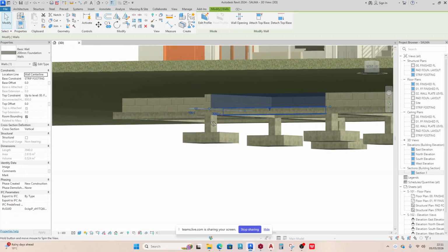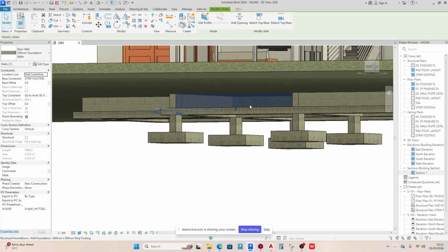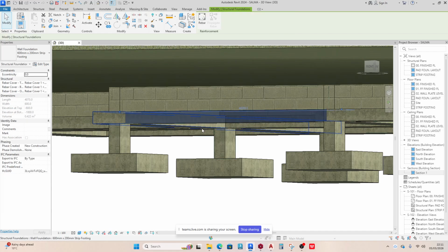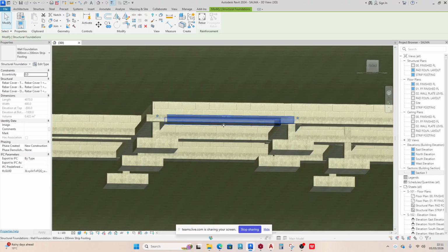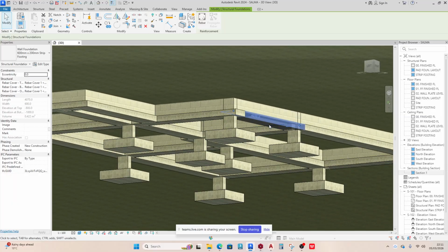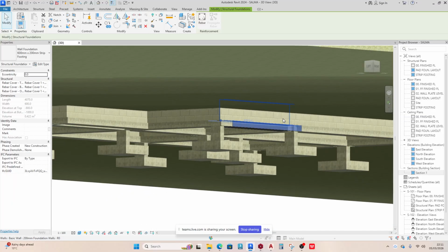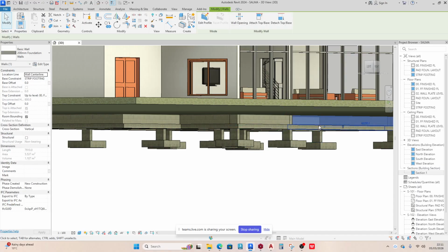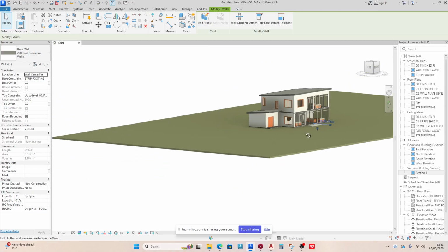It wouldn't work properly. You need the weight or the loading of these walls to be distributed evenly into the soil for better bearing. Otherwise, the settlement would be massive. It wouldn't be a stable structure, to put it short.